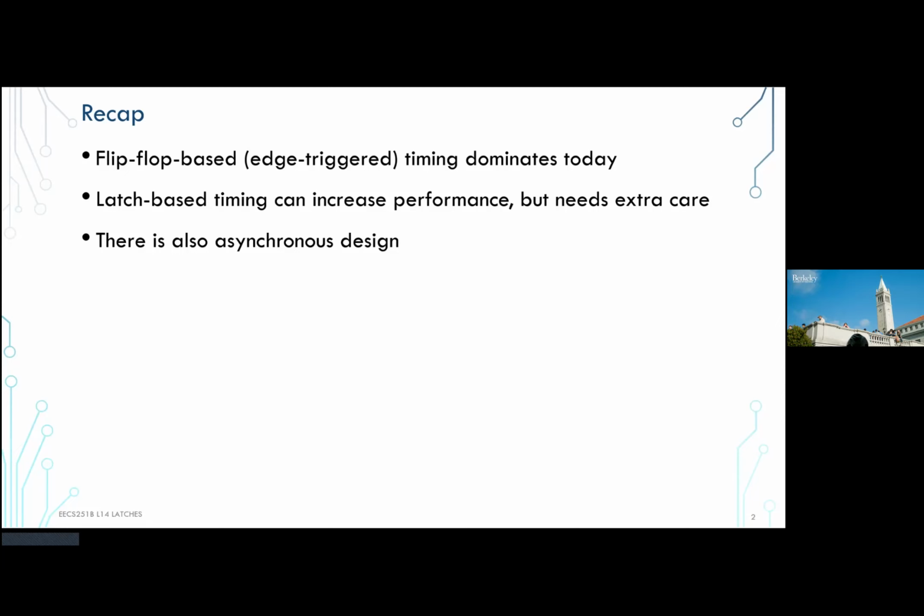Again, we need to make sure that we are correctly constraining this for every cycle or for every half cycle, such that we know when this time borrowing is happening. And this is done by the tools automatically if the design is done correctly. And when you read these timing reports, you will actually get the amount of slack that is being passed.